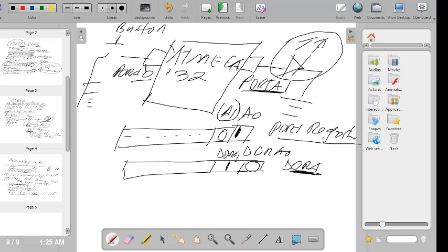I want to mention here that when you get an ATmega chip, an empty ATmega chip, these ports can be configured either as input ports or output ports. If you don't define your data direction register, then you have a problem in running the chip, because the ports do not know themselves whether they're input ports or output ports. Then you yourself have to configure it through your assembly code.